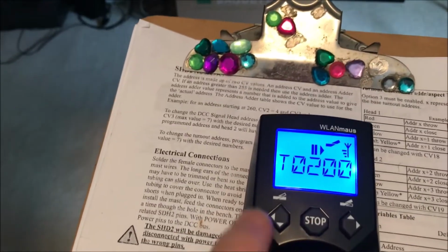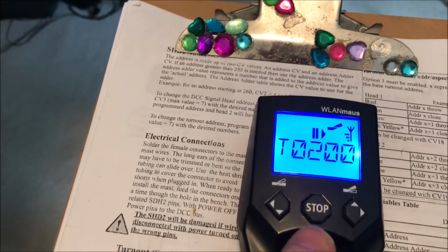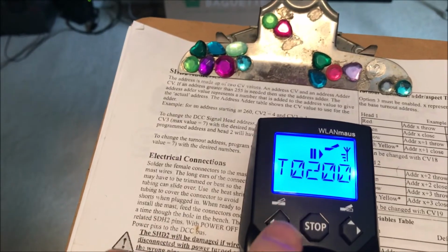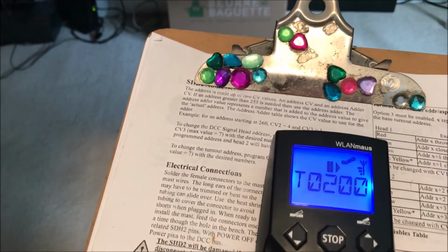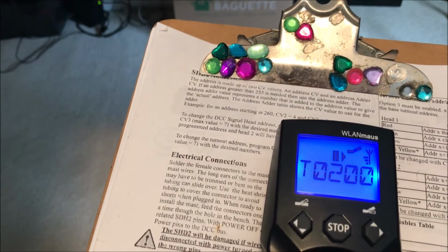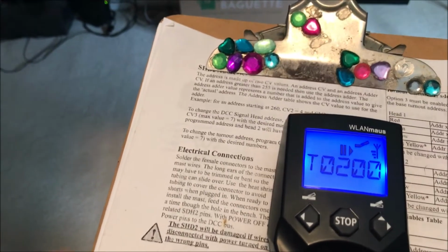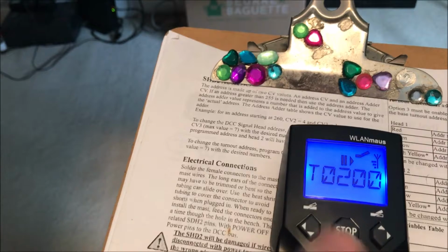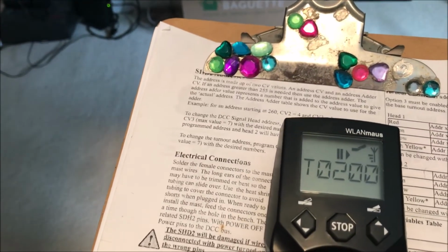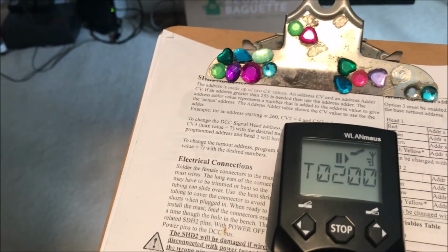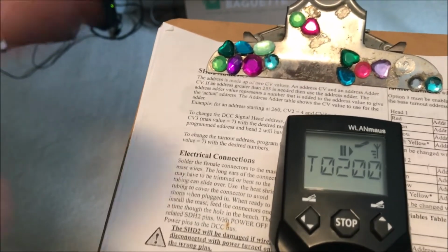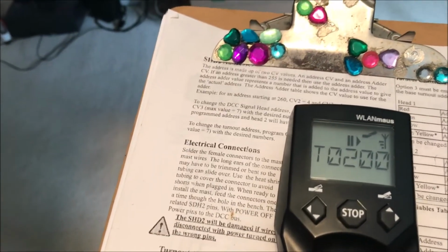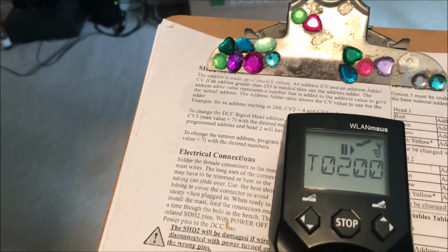But what happens is you can't double up on the same address. For instance, if you use a turnout address and it's, let's say, 200 for that signal, but then on the layout somewhere you have an address 200, well, when you flip it, the turnout will flip, and then that signal will flip. So you have to remember to keep a batch of numbers for your turnouts, and then a batch of numbers for your signals. I didn't like that idea.